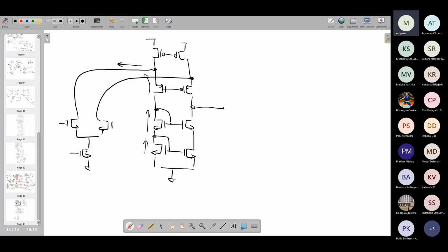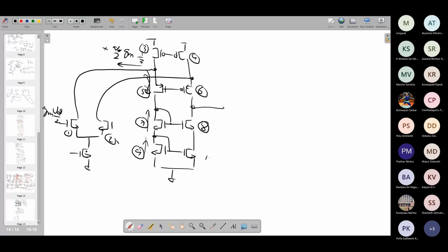So now in this particular example, you can see if it is your M1, M2, and you are getting say gm Vd by 2 plus gm Vd by 2, and as we have seen, 1/3 of that will go inside gm Vd by 2. So this goes into this, and these two transistors, if I call this 1, 2, 3, 4, 5, 6, 7, 8, 9, 10. So if you look at the M7 and M9, they are effectively once again mirroring the small signal current into M8 and M10, right?